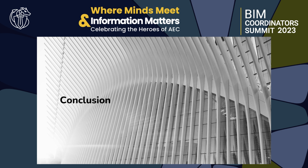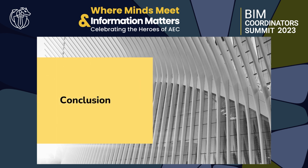AR VR visualization are technologies that enable immersive and interactive visualization of BIM models and data. Field verification via point cloud or laser scan. 3D laser scanners capture a high density point cloud of a physical building, structure or site, which is then used to create and maintain a BIM model that reflects as-is conditions.